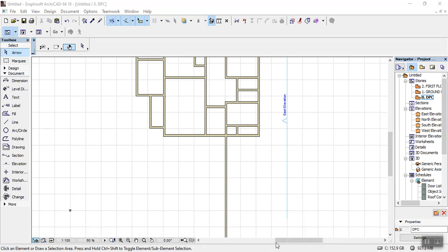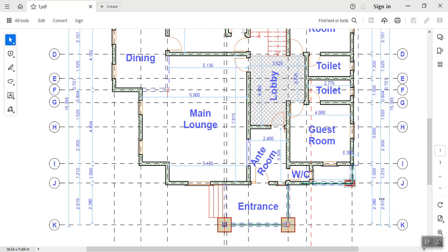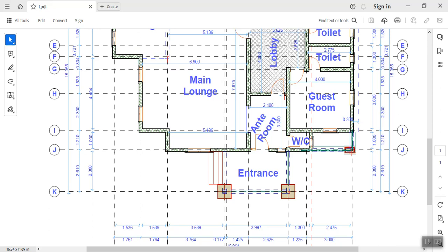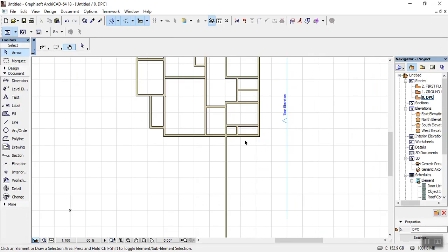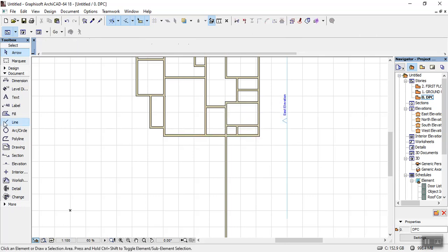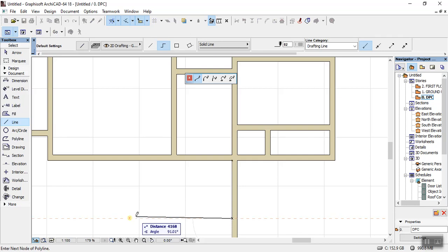Let's see what we got here. What's the entrance? We have the entrance of 2.380 by, let's say, 3997. Let's just do it 2.380 by 4 meter. Let's go 2.380 height. So I'll take my line tool because I don't want to use my calculator to do plus up. 2380. I'll drag it to the spot, and I'll make this place 4 meter, preferably 4 meter.